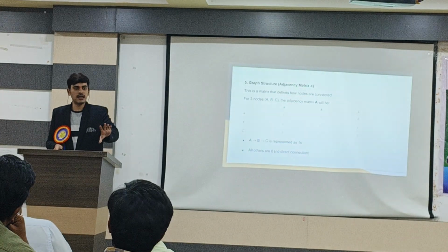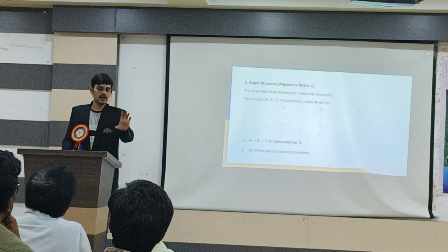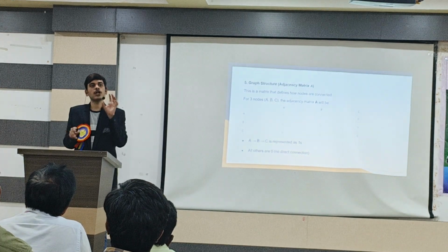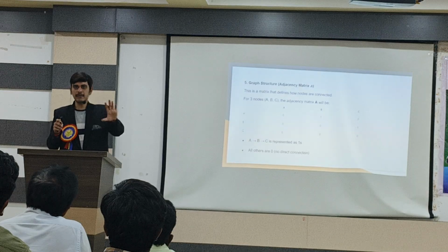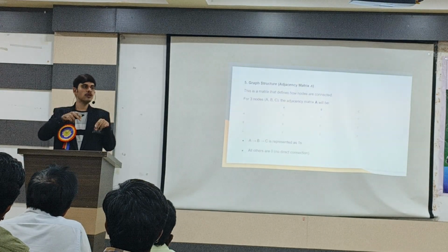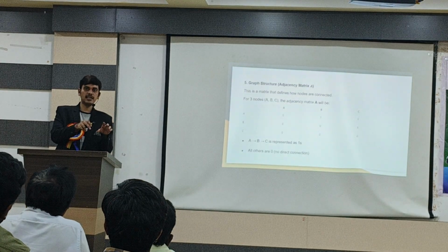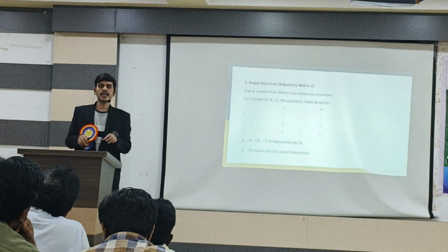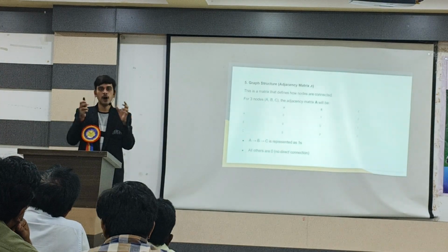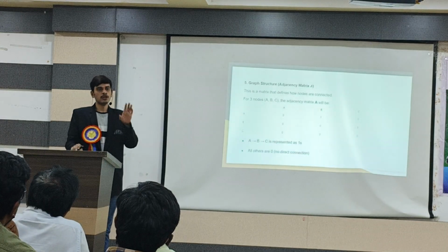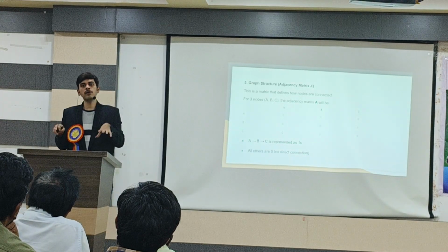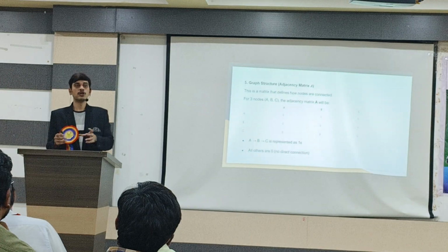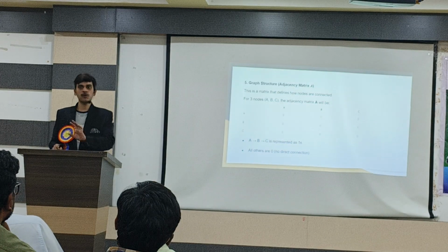They allot the area, for example, 100 units for audio and 50 units for video, based on the application, for the logic level. They run it one time initially, because the individual block owners will give a synthesis at least, and the top owner will take all of them together. So he gets the overall timing and area, like how many cells there are and how much area the cells take. Based on that, the top owner allots the area to each block, and the individual block owners work within it.